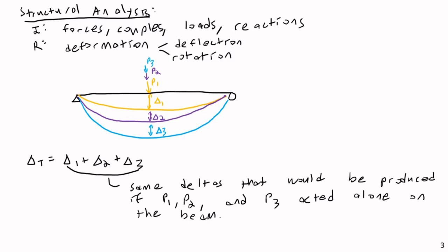But where it's really useful is where you have cases of multiple different types of loading on a beam. Obviously, if I just did 3 different point loads at the same point, it would be trivial just to add them together into 1 point load. But where this is exceptionally useful is where I have multiple different types of loading at different places on the same beam. This is exceptionally useful for beams with complex loading, and really structures with complex loadings in general. This doesn't just apply to beams, it also applies to frames and trusses.